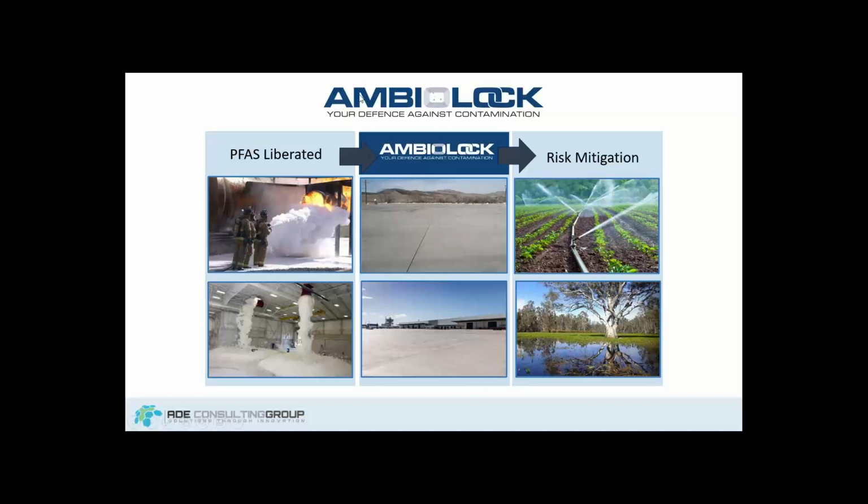The aim here is not to exploit the chemistry, but instead of stopping the PFAS moving into the water, we're stopping the water getting to the PFAS. The goal here is to also produce something useful. So through producing concrete from PFAS impacted materials, we can stop water moving through the solid phase and transporting the PFAS out of the matrix. And obviously the PFAS is trapped physically in the concrete as long as the concrete is solid, and it can be recycled and reused.